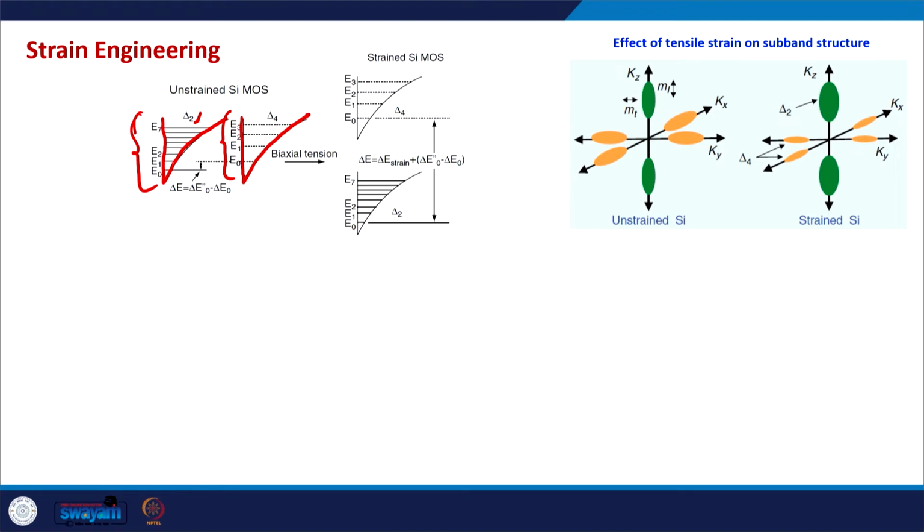And as you can see, there is a difference between the ground state energy of these two valleys, and this difference is there because of the quantum confinement in y direction. In bulk silicon generally this difference is not there, but because of the confinement this degeneracy is lifted at the interfaces, in the inversion layer of the MOSFET or in the ETSOI MOSFETs.